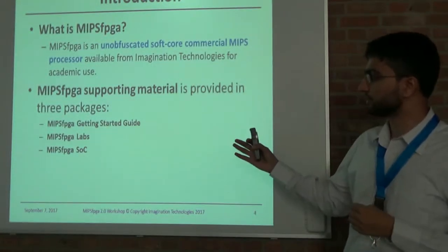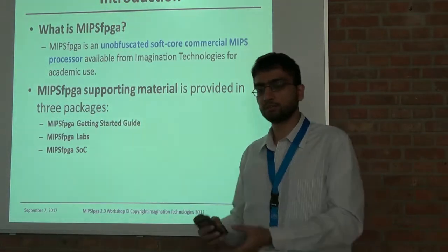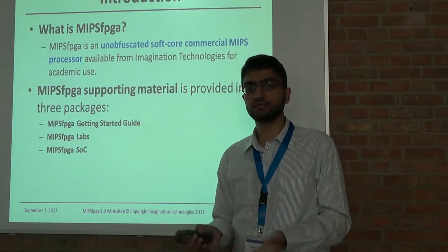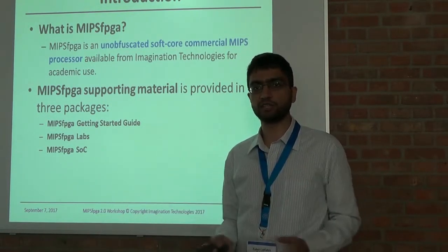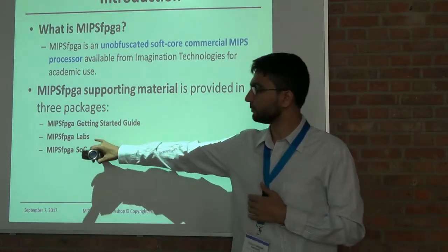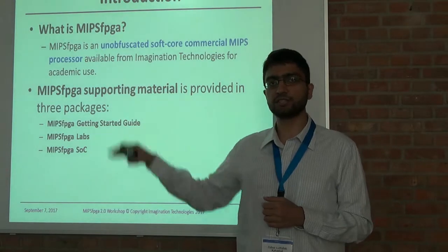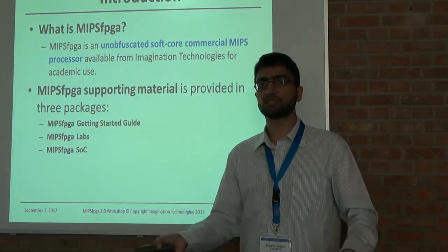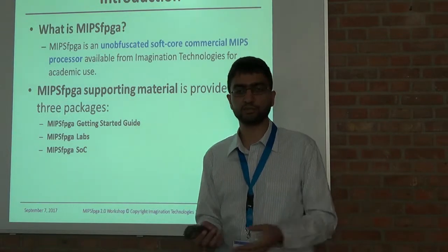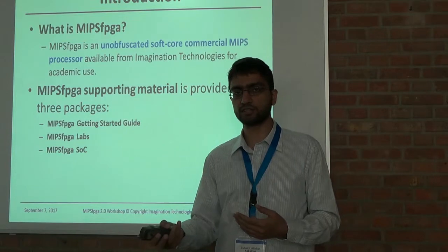There are 3 packages. The MIPSfpga Getting Started Guide talks about the interfaces, how the IP core can be brought up: the clock, reset, power, and various interfaces around it. Then we have MIPSfpga Labs. These are a set of 25 labs which increase in complexity as you go. It starts off with very basic things: how to load the bit stream on the Nexys 4 DDR board, how to compile some code and load it using the JTAG debugger.